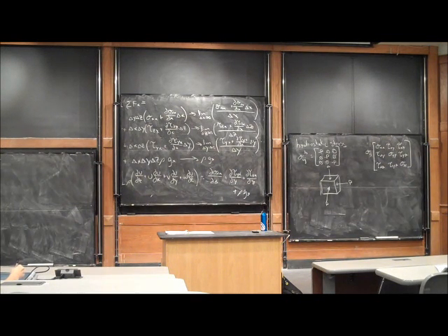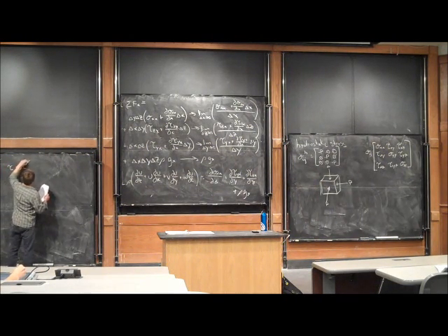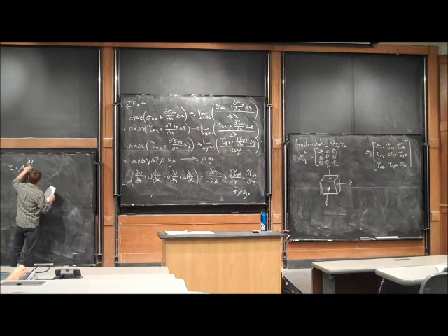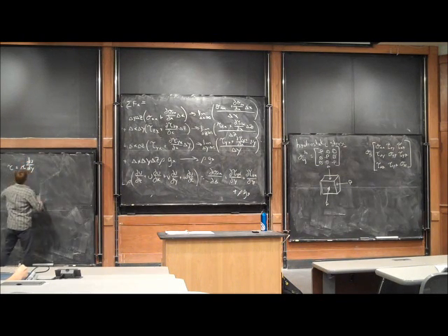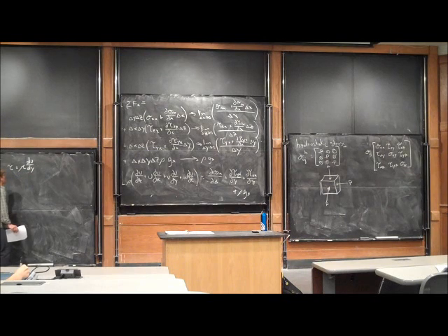We said the viscosity was defined as tau equal to mu del u del y, or in this case, because it was one-dimensional, they were actually complete derivatives, not partial derivatives. So this was actually a simplification of how we define viscosity.